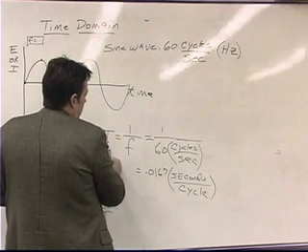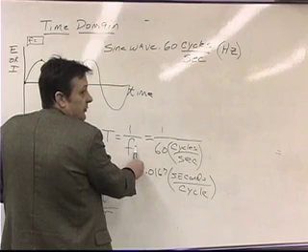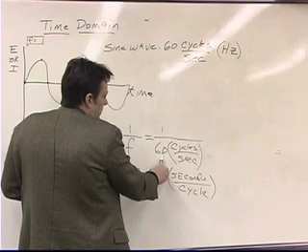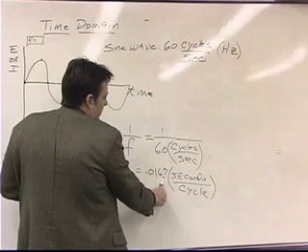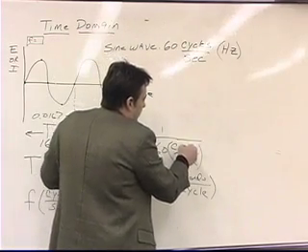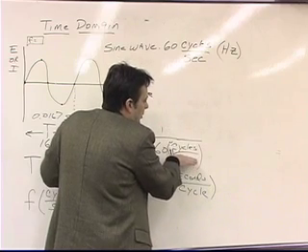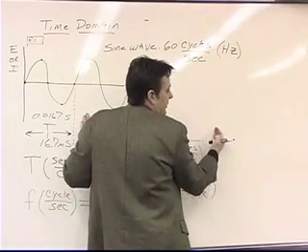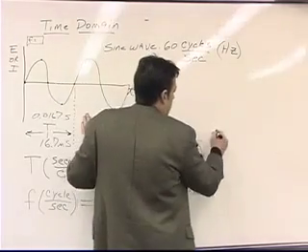So we wanted to find what the period was in a 60 cycle system. Period T is equal to 1 over F, the inverse of frequency, which is 1 over 60. Our calculators told us that it was 0.0167, but when we have cycles per second in the denominator, what are the units going to come out as when they move up into the numerator? Seconds per cycle.